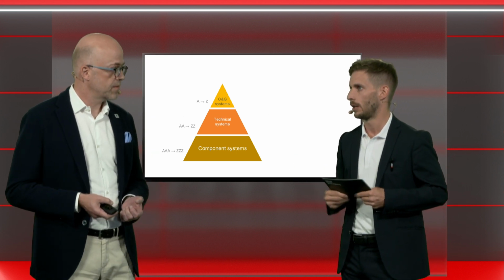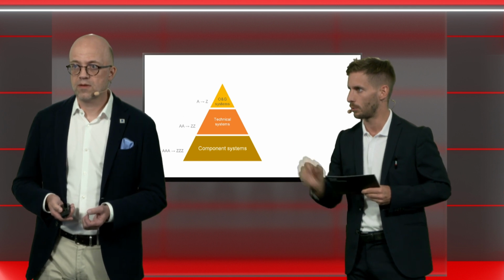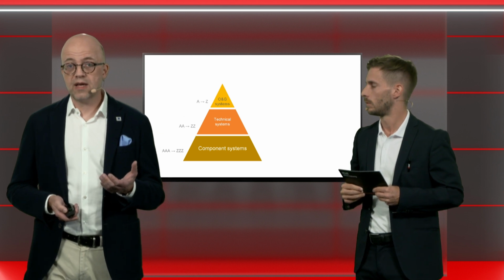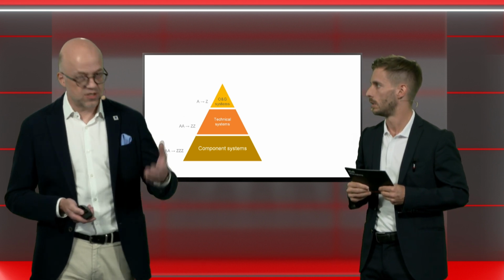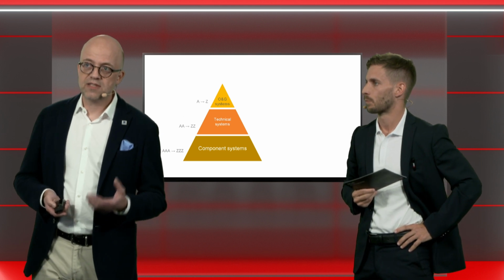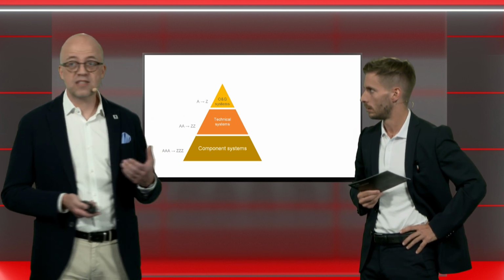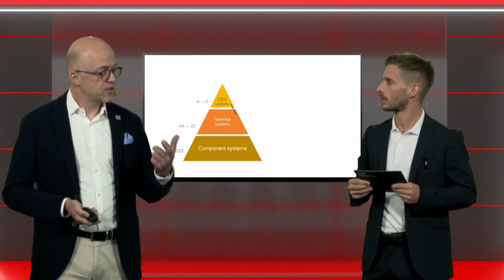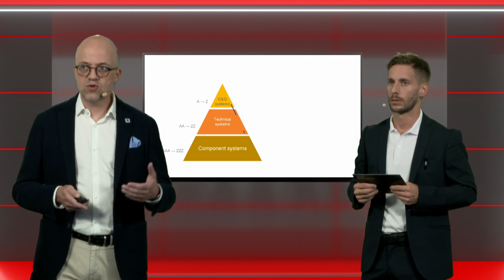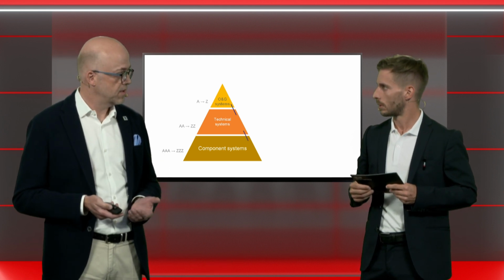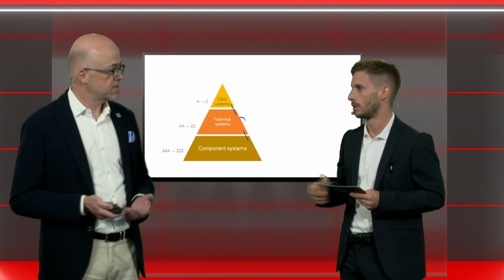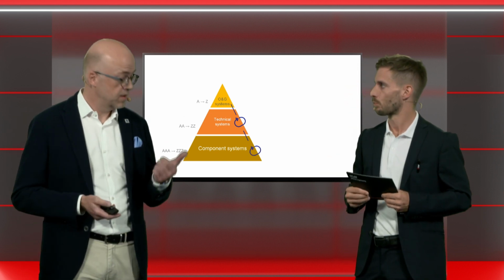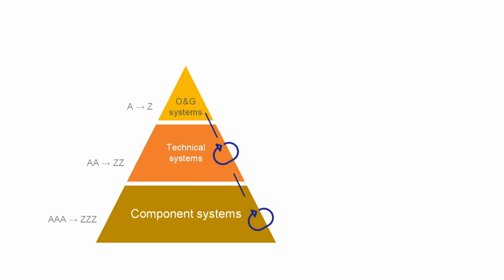Really nice. What do these letters stand for in these 3 levels? I'll show that in a moment. But before that, I would like to show you a technique for how we put systems into systems. You can have a technical system which is a part of a main system, in this case a big oil and gas system. And within that technical system, you can aggregate your component systems as well. The trick is to avoid always having 3 levels. You can also put a technical system inside a technical system, and a component system in a component system. That allows you to have more than 3 levels. So you can have 1, 2, 3, 4, or 5 levels.